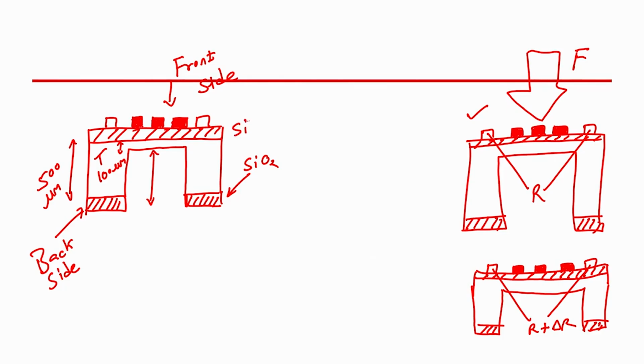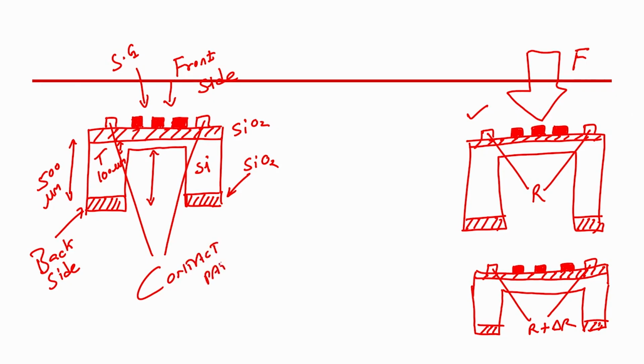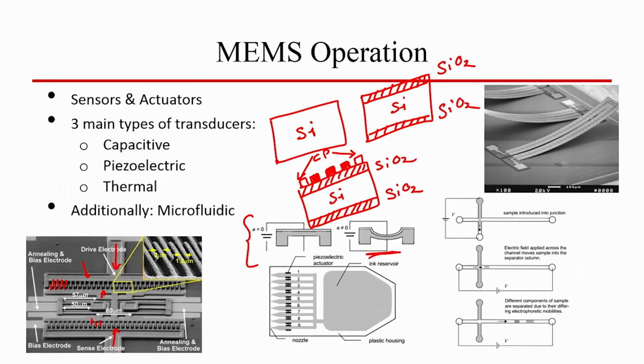This will be my silicon dioxide, this is silicon, this one is my strain gauge, not any more material because we have patterned it, and this one are my contact pads. Alright. So, we got this, right. This is how the micro machining works, in particular bulk micro machining works. Okay. So, this was about your MEMS operation.